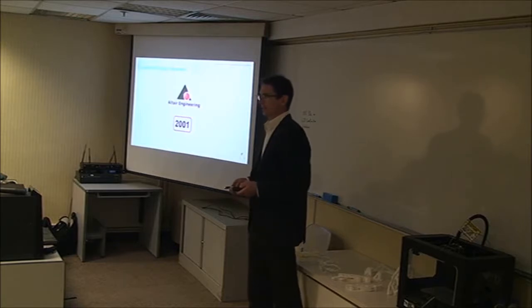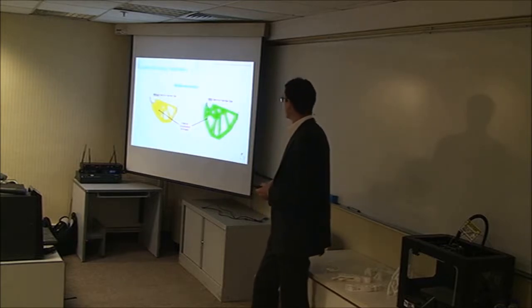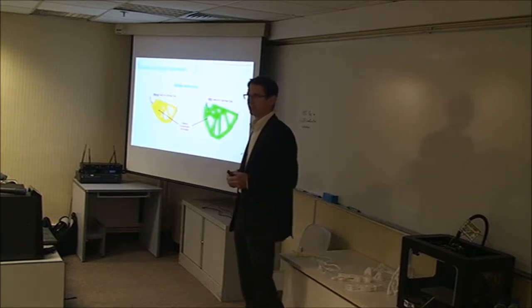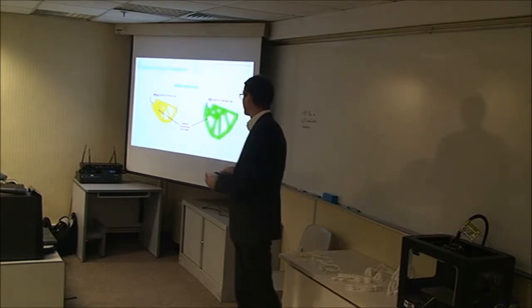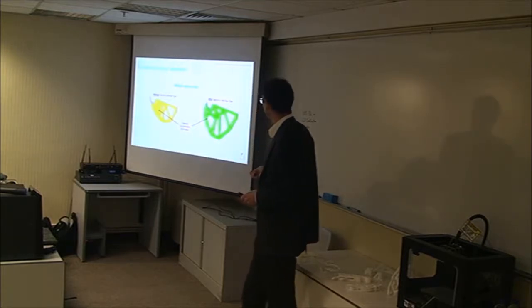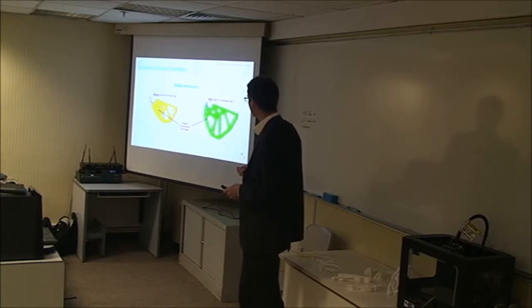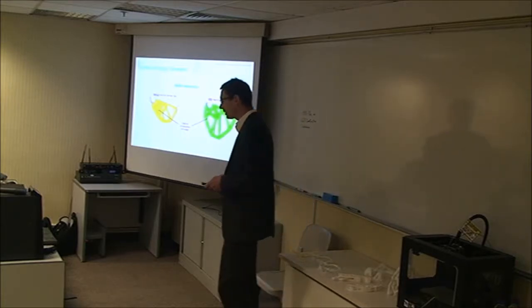But we saw that a lot of other industries would like to use this optimization, but then they said, hey, I cannot produce what we generate with our optimization. So our engineers sat down and introduced manufacturing constraints. They guide the optimization towards a certain direction. Max member size, for example, for molding processes, where you try to avoid regions with a lot of material because it shrinks and then you get problems.